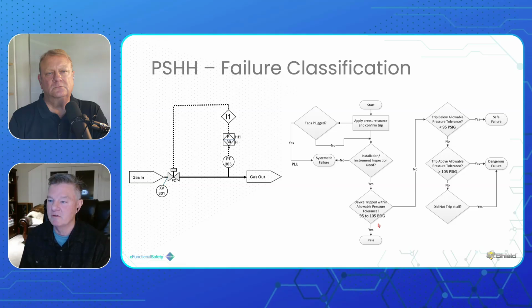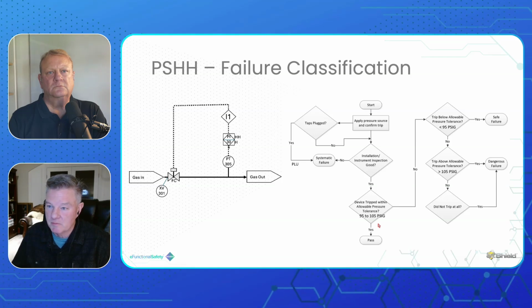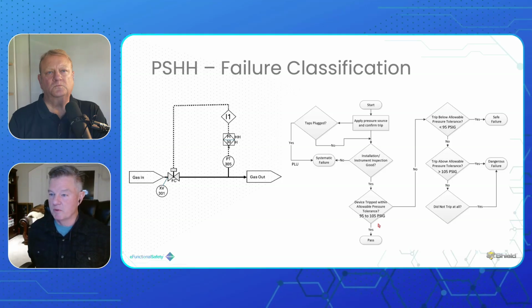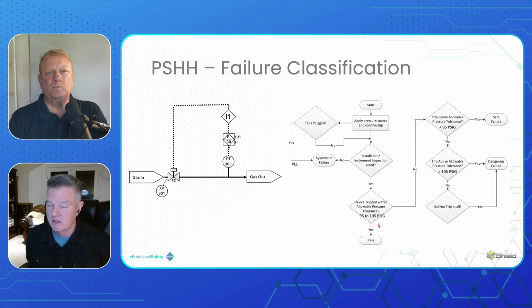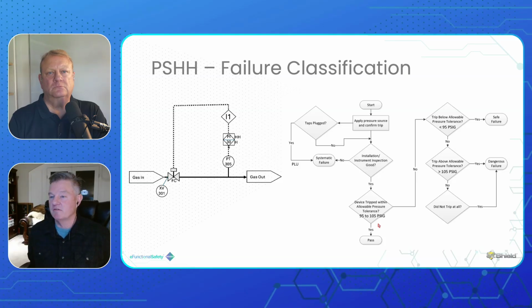For instance, if I had two transmitters and I compare them together, and we've got a 100 millisecond scan rate on the control system, in the safety PLC, you're having a test basically that's saying, do these two vary by plus or minus 2%, 5%, whatever the number is? It's happening every 100 milliseconds. That's a phenomenal test. That makes lambda DU 95% lower than what you've got. That's finding it when it occurs instead of waiting for testing to find it.